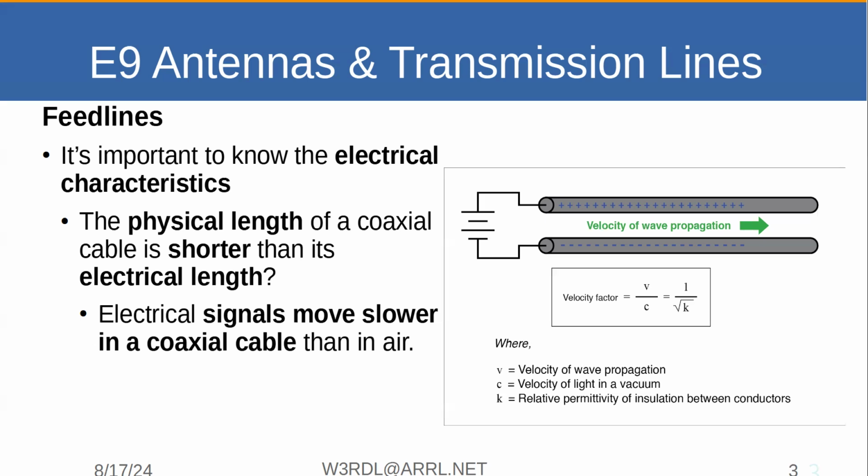Is there a particular velocity factor? It looks like it's 0.95. Bare wire is a lot lower than that. Well, most of your coaxes are going to be lower than that. Probably at best, maybe 0.88, something like that. And they go down, let's see, as low as 0.6, which makes for short lines physically.